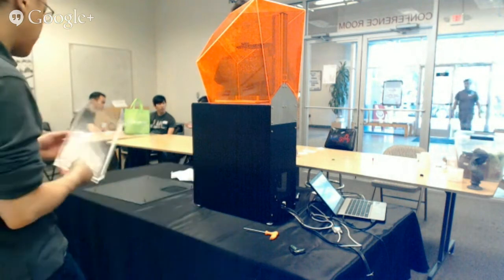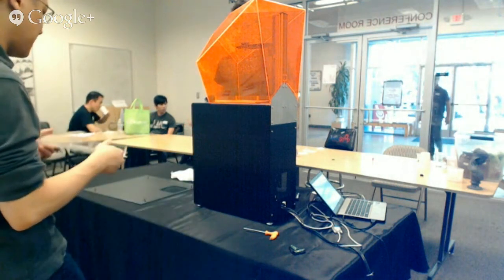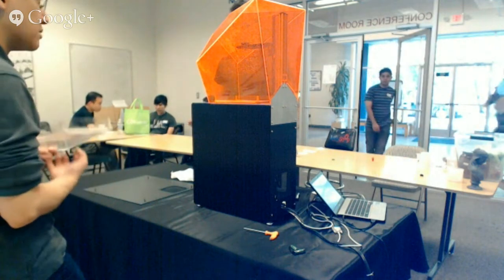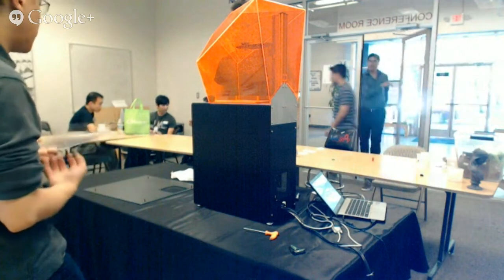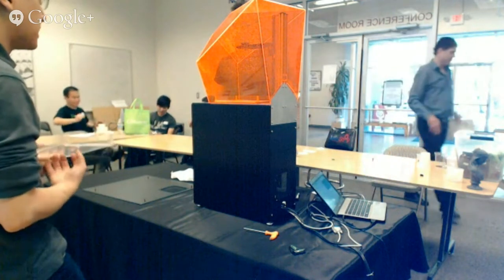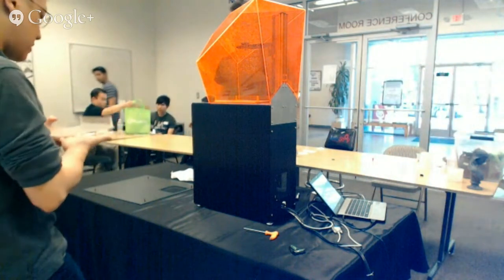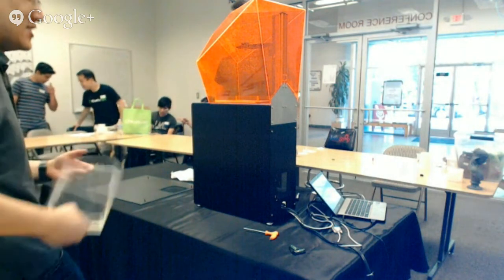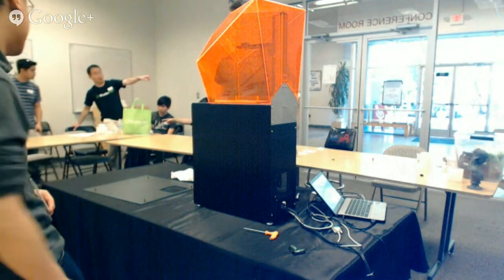I tried to design my own flex vat, printing on PLA. It's hard. Designing that is difficult. The tensioning system is very difficult. You need to hold the film under a lot of tension because it's got to be flat. If it sags, you have all kinds of problems with the layers not being even. Yeah. Okay.